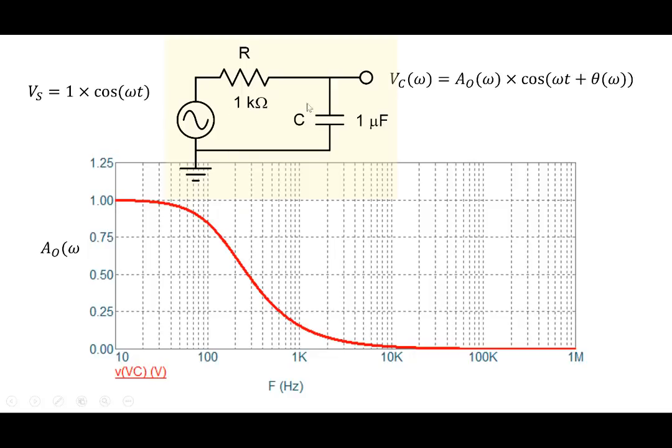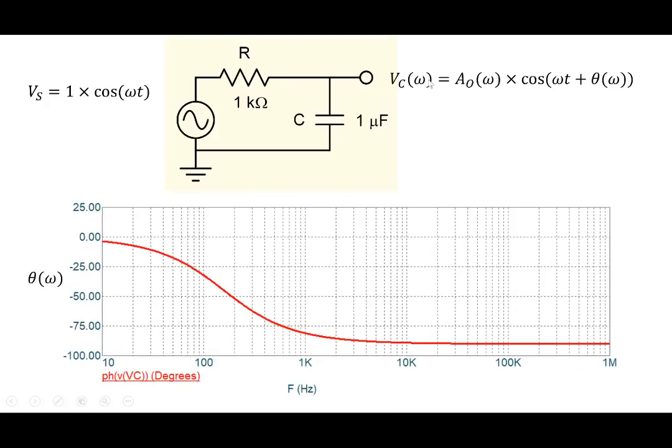That this circuit acts like a low-pass filter here. And the phase value, if you go and look at the other part, the phase value starts from 0 and then eventually goes towards 90-degree phase here, right? So the signal that comes out initially for very low frequencies, the phase is very close to 0. So, as we said, the circuit is transparent to low frequency signals. The signal that you apply here just appears over here.